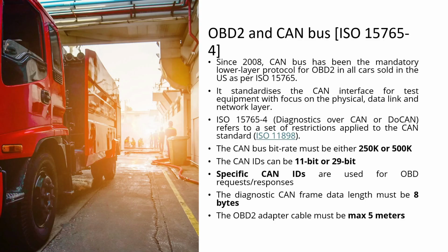Since 2018, CAN bus is made as a mandatory lower layer protocol for OBD2 in all cars. It standardized the CAN bus interface for test equipment with focus on physical, data link and network layer. The standard number ISO 15765-4 is meant for integrating OBD and CAN bus.